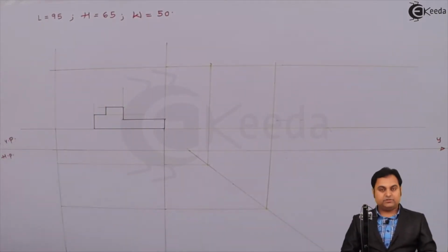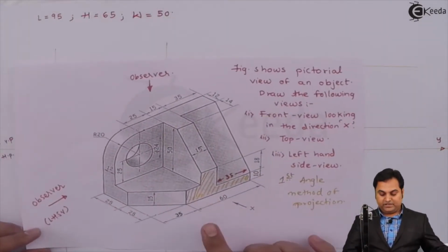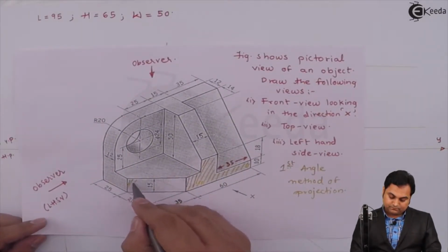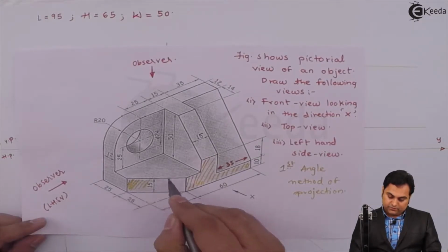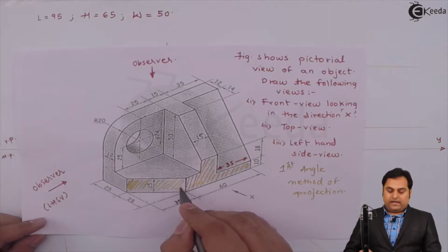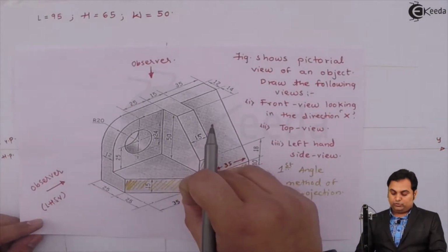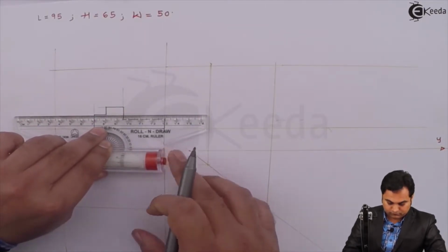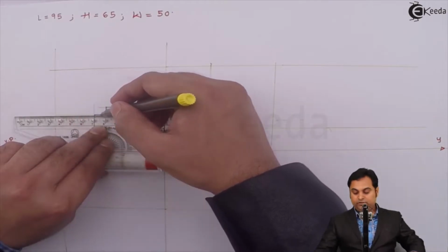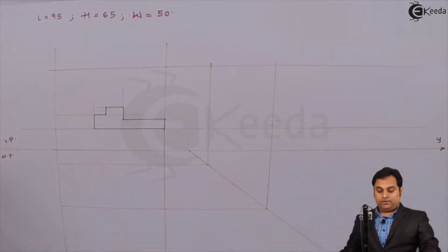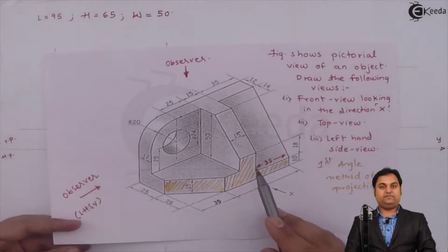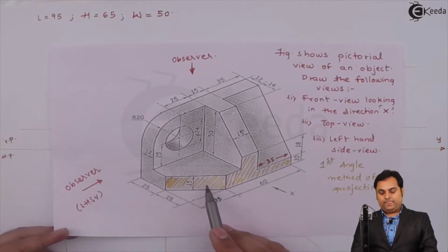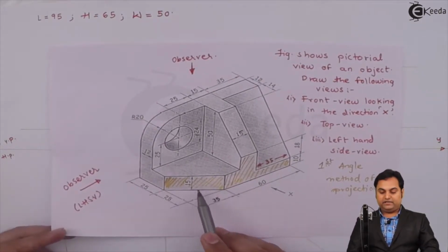So this is the surface which is visible first. I have made it dark. At the same time, this inclined rectangle will also be seen from the front, and it is also having 15 height and up to the total length. Projecting a light horizontal line. Now if we see here, then this surface which I have drawn first and now the inclined rectangle, both are on different planes. So that is why in between them there should be a dark line.